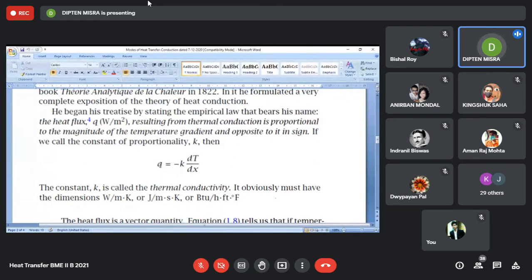And it is a matter of practice that if you are asked about the unit of this, you should be able to memorize it. Or if momentarily you forget, you can derive the unit by dividing the unit of heat flux by the unit of temperature gradient, and then it will evolve out as watt per meter square per Kelvin per meter. It will be watt per meter Kelvin.